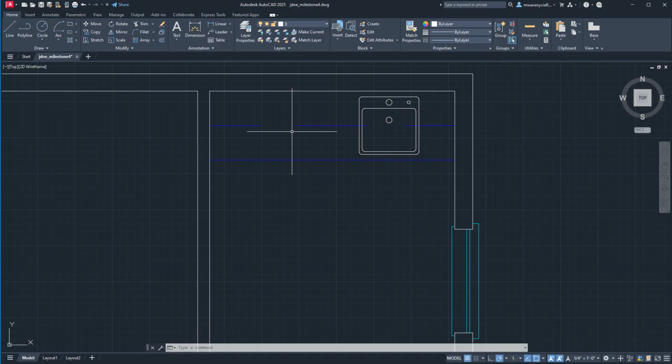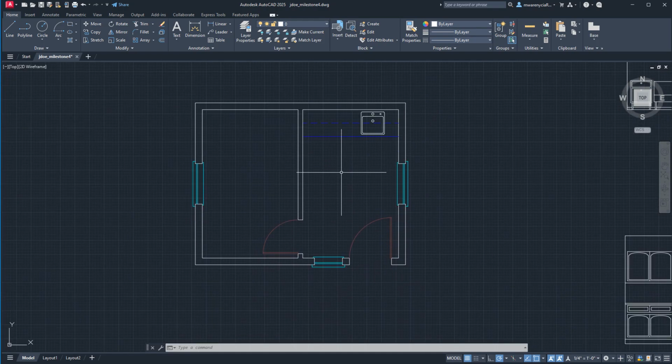So the way to manage this is you're going to type LT scale. This is going to set a default line type scale. What we're going to do is type 16 here, and if it gets better, we're going to use that, and if not, we're going to do 1/16, and that's too fine. So that just helps me establish where I am in this hierarchy. It looks like I want to go sub 1, I want to do a fraction. So instead I'm going to do 1/4 inch, and that's what I'm looking for right there. There's a couple decent dashes right there. That's what I'm going to want for this.